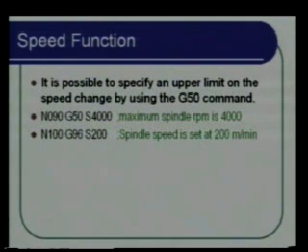For example, sometimes a chuck may have a limiting RPM. Though your machine is capable of going up to 5000 RPM, if your chuck has only capability to go up to 3000 RPM, and you try to run it at more than 3000 RPM, the chuck jaws may come off and the workpiece may become loose and fall off the chuck. So we have to limit that speed.